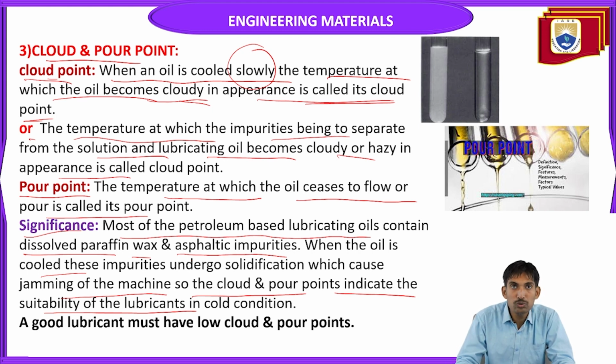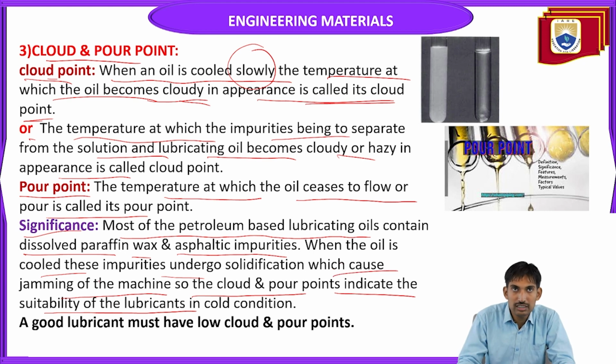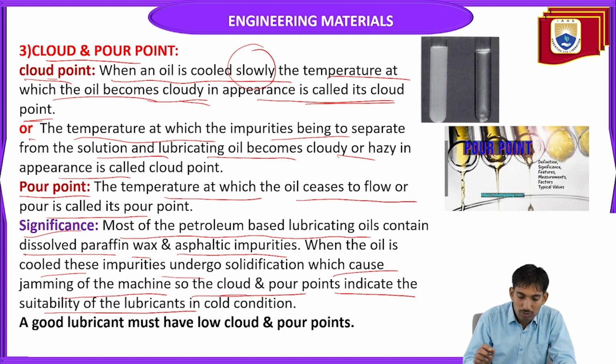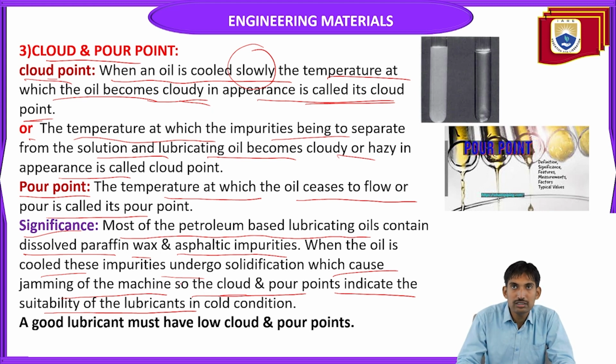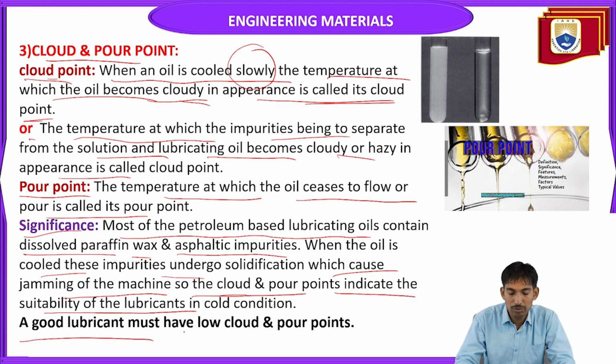When the oil is cooled, these impurities undergo solidification, which causes jamming of the machine. So the cloud and pour points indicate the suitability of the lubricants in cold conditions. A good lubricant must have low cloud and pour points.